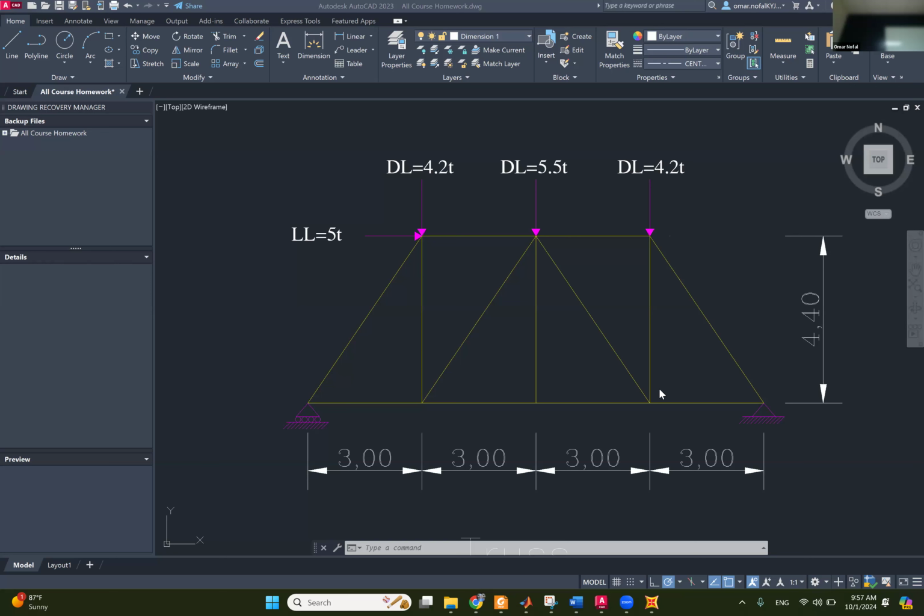What we have to do is make sure that the information that you put inside the software is good. Like for example, this load direction needs to be in the positive X. If you did it in the negative X, your problem is not right. If we are putting a load on a slab system, the load needs to be in the gravity direction. If you put it in the Z direction, that means the load is going to go up. So the slab, rather than bending down, is going to be bending up, and the deflection is not going to be right.